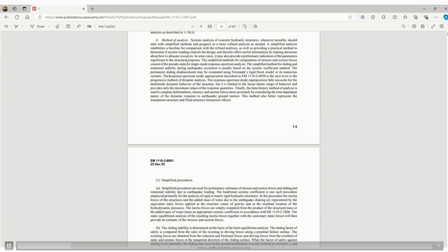We can plot a curve between that. So it will give the maximum response at a particular time period, and that will define the boundary condition in the frequency domain for that structure. But we are not simulating the ground motion for each time cycle. We are not evaluating the behavior of the structure. So this is called the response spectra method.